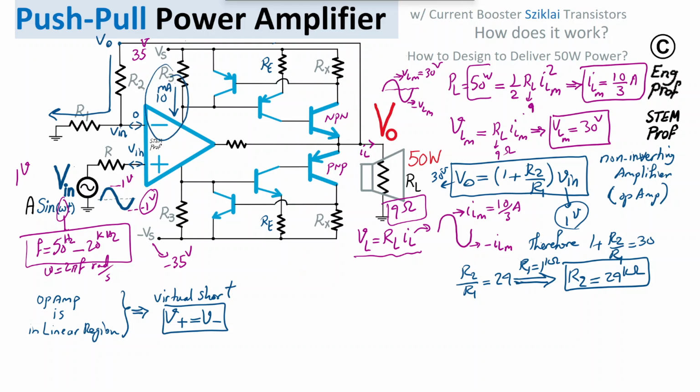So if 10 milliamp is the nominal DC bias current for the op amp, I just need enough voltage drop across R3 so that this combination of the series RE and the emitter-base of T1, T2 is just about to turn on. If emitter-base requires about 0.7, as an example, I can set the default nominal voltage drop across R3 to be 0.7. In some applications, maybe we need to set that to 0.6. It's just a matter of how much potential dead zone we can tolerate in this system, because we want this to be a class AB push-pull amplifier.